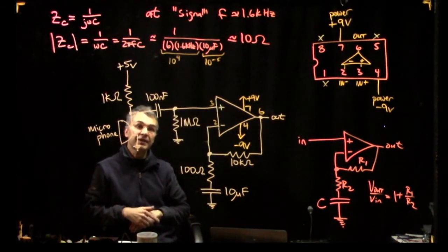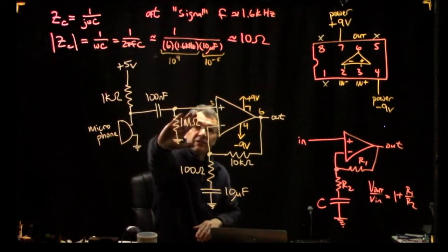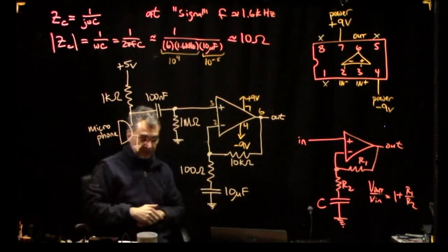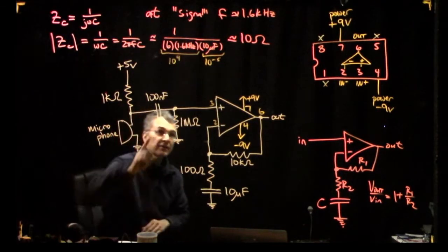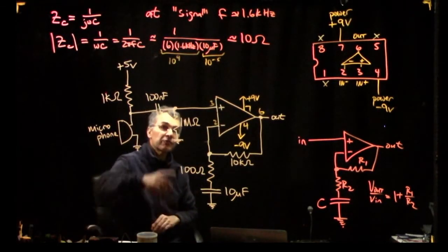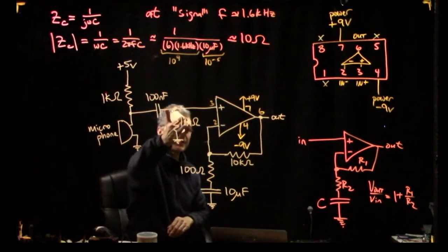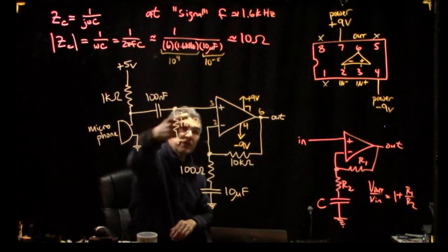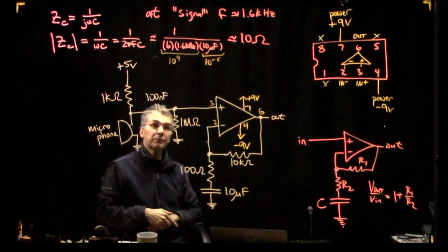So that's all fine. But if we didn't have this resistor, then the bias current, there is a small bias current. It's like tens of nanoamps for the 741. It's like about 100 nanoamps. And it flows into the 741 input.